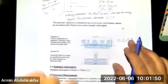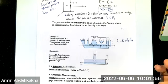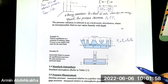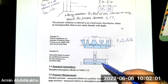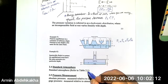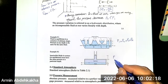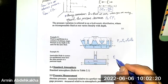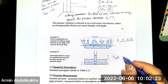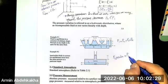The second thing is that when two fluids that cannot be mixed, like gasoline and water, are in close contact but in an equilibrium state, the pressure at the point at the interface is the same. So if that point is 1, P1 of gasoline is equal to P1 of water.